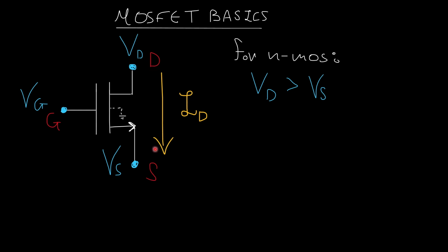And there is actually a fourth terminal, which we usually don't draw, which is between the device and the ground. It tells me some things about the nature of the gate here. The gate is actually connected to this terminal, which connects to the ground in the form of a capacitance. So this is like having a capacitor here. That's why we also draw it like this. So at small frequencies, I expect no current to flow from the gate inside this device.